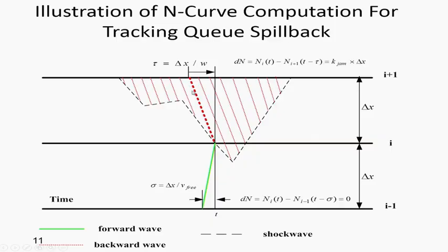Those are the result of car following. Those backward waves will be propagated throughout this space dimension, and finally along this dashed line, I would like to say 1 minute before you have a congestion, and then throughout this backward wave line, this congestion will be propagated to node I at this particular time stamp t, so that this whole intersection or this whole section will be congested.